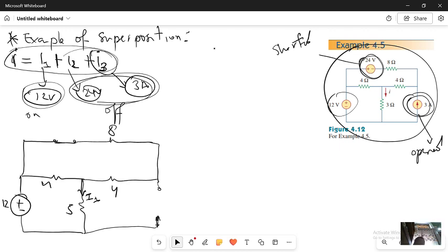Now, how can I determine the value of I1? I have to look at the circuit and use the methods that we learned in the previous video. The current will pass from here. No current will flow here, because it is open. The same current will flow through this 4 resistor. This means that this 4 and this 8 are in series, so 8 plus 4 equals 12. I will reduce my circuit to a smaller circuit, with 4 and 12.